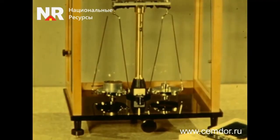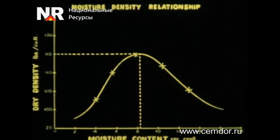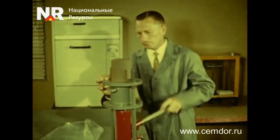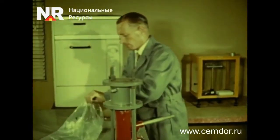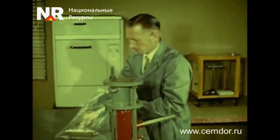A graph is plotted showing the relationship between the dry soil density and moisture content. For cohesive soils, the maximum density value and the corresponding optimal moisture content are determined from the highest point on the graph. To determine the optimal dosages of stabilizer and cement, several mixtures of different compositions are prepared, varying the content of the added components. This is done with a specific increment.